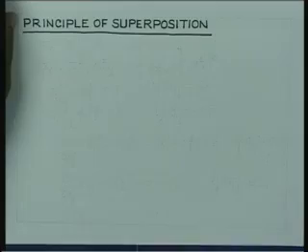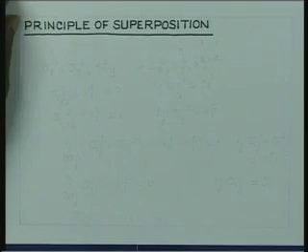Now, we would like to consider this second theorem, which relates to the principle of superposition. If you have a body and it is subjected to two sets of loading, then the stresses for each set of loading can be added together to get the stresses corresponding to the two sets together.